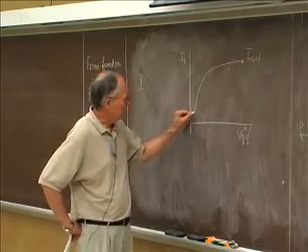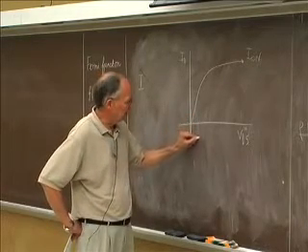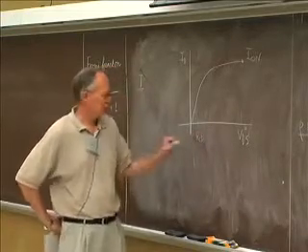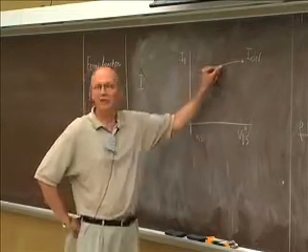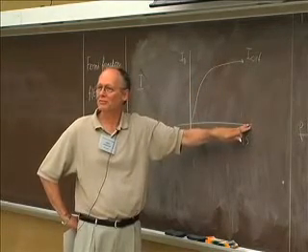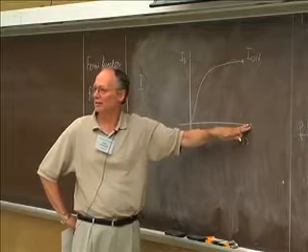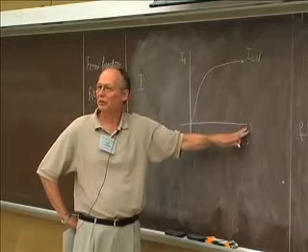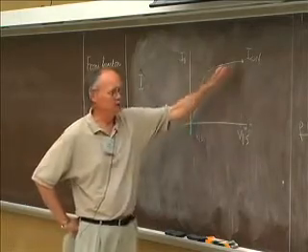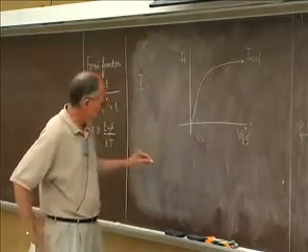And you would also like the channel resistance down here to be as small as possible so that the current goes up very rapidly and saturates, and it doesn't take a large drain voltage in order to saturate, because power goes as voltage squared, so you could operate at lower voltages. So you'd like this curve to be steep and you'd like this value to be high.